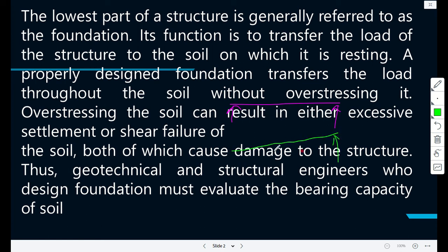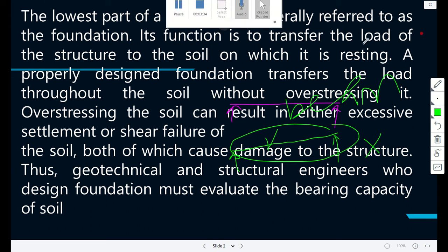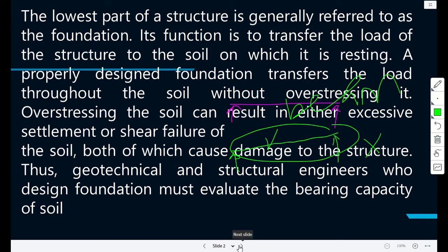If this is a beam, from your structures you can calculate the stresses, but we don't need this. This would induce a lot of stresses in the beam, and your beam might fail. This is what we are trying to say: you should take care of the foundation such that the settlements are within reasonable limits, so that the structures are not destroyed.